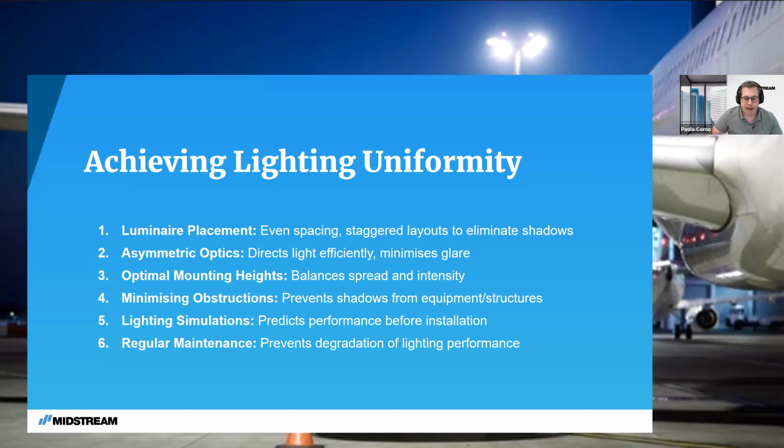So understanding and taking that into consideration in a lighting design, by adding, for example, the 3D models of it, will allow you to avoid going to install after you did a simulation just based on a flat AutoCAD drawing. Then you realize that half of your luminaires are actually blocked by a building. So instead of having some light there, you have this massive black cube and black square on the ground.